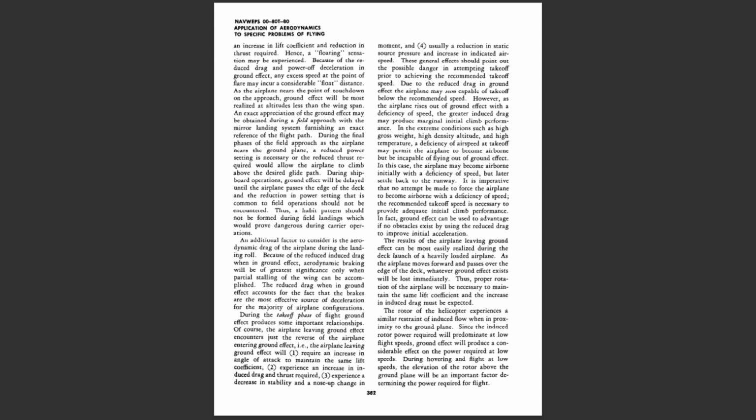The results of the airplane leaving ground effect can be most easily realized during the deck launch of a heavily loaded airplane. As the airplane moves forward and passes over the edge of the deck, whatever ground effect exists will be lost immediately. Thus, proper rotation of the airplane will be necessary to maintain the same lift coefficient, and the increase in induced drag must be expected.